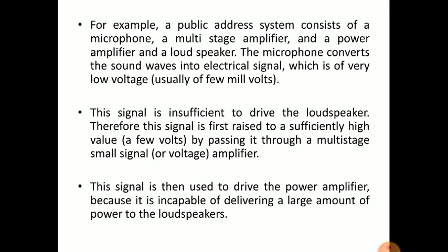The signal is insufficient to drive the loudspeaker, therefore this signal is first raised to a sufficiently high value, that is a few volts, by passing it through a multi-stage small signal amplifier. Small signal means here voltage amplifier. The signal is then used to drive the power amplifier because it is incapable of delivering a large amount of power to the loudspeaker. There we need a power amplifier.